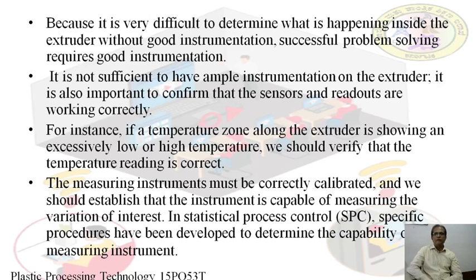Because it is very difficult to determine what is happening inside the extruder without instrumentation, successful problem solving requires good instrumentation. It is not sufficient to have ample instrumentation on the extruder. It is also important to confirm that sensors and readouts are working correctly.